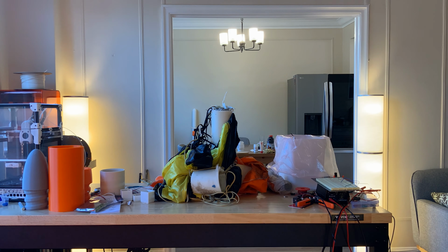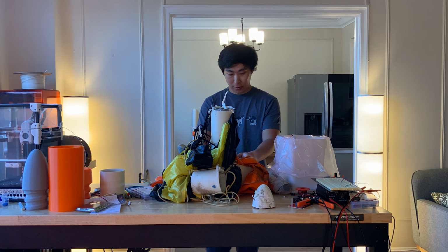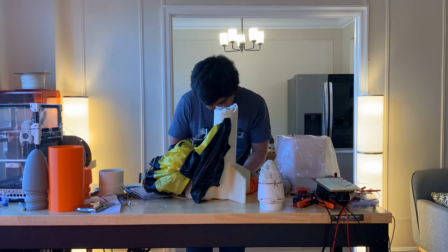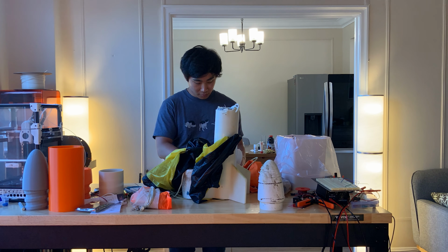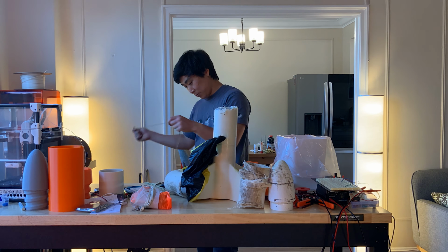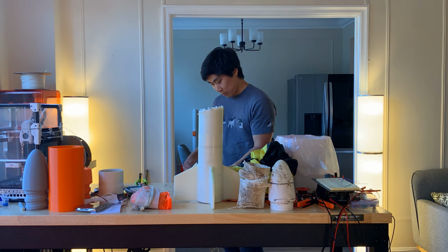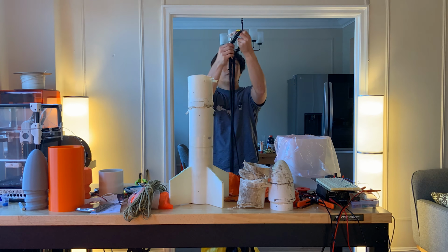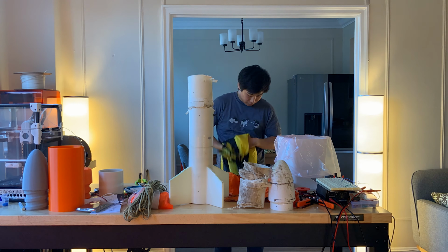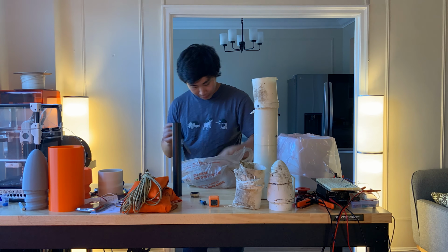With some investigation, the parachutes failed to deploy due to an inadequate amount of ejection charge, which I would have found out earlier if I had ground tested it. With all this, I was super fortunate that only my rocket was damaged in this flight. After all, these things can be rebuilt. Next time, I'll be sure to check off all my boxes before launching to avoid another expensive lesson like this.